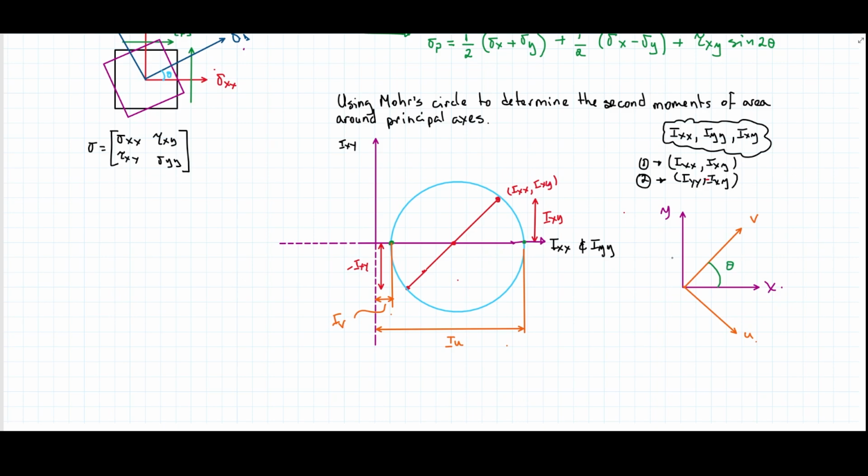But it might be possible that you don't know the orientation of the neutral axis. And why is the neutral axis important again? Well, because deformations are going to happen around the neutral axis. So you need to know the direction or orientation of the neutral axis if you want to know how that thing is going to deform. It might be different, and that is usually represented as having an angle alpha with respect to certain other axes. That's something to keep in mind.